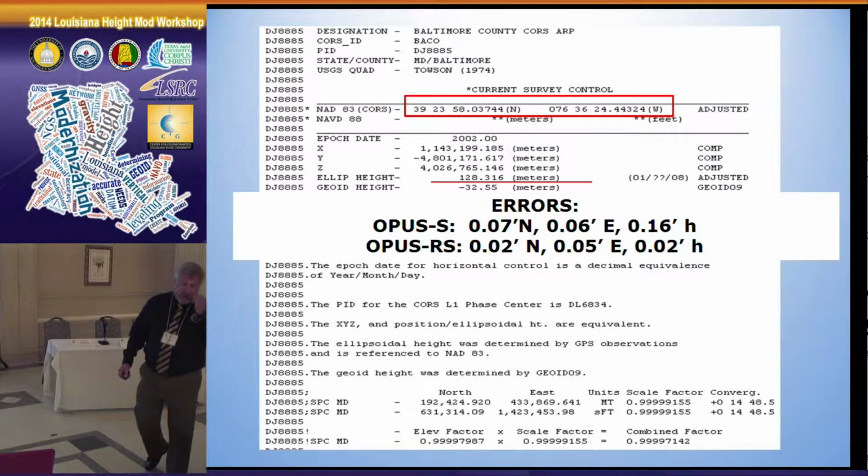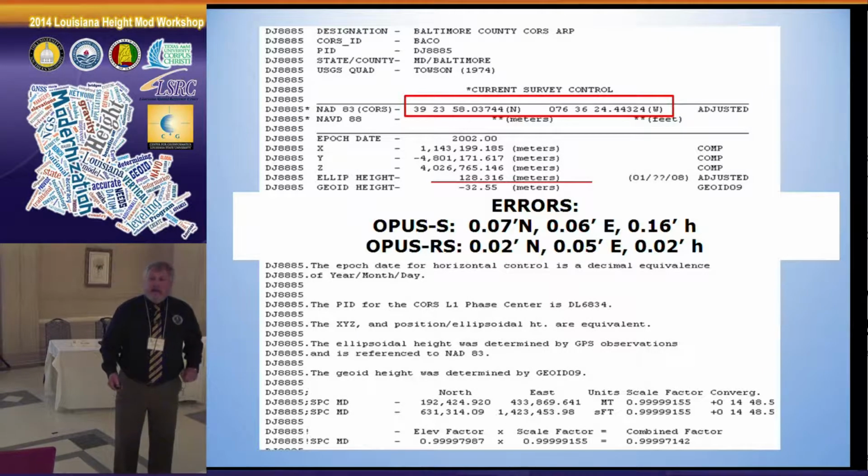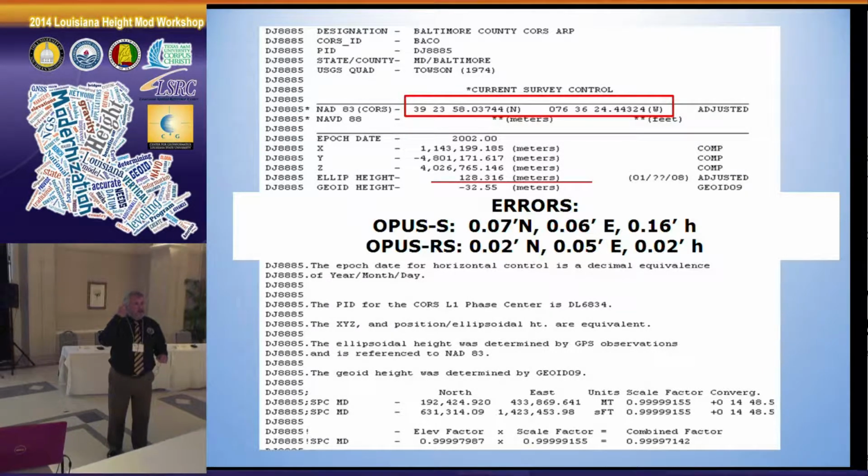So what's the point of all this? Two points. Number one, you can convert your files to RINEX files where you can edit them as text with a text editor, Notepad, or whatever. Make sure you don't get any extra carriage returns or anything like that. But you can edit your files. If you have a 4-hour file, you can chop it into sections. You can submit those sections to OPUS Rapid Static. Or if you have 2 hours or less, you can submit them to both of them.